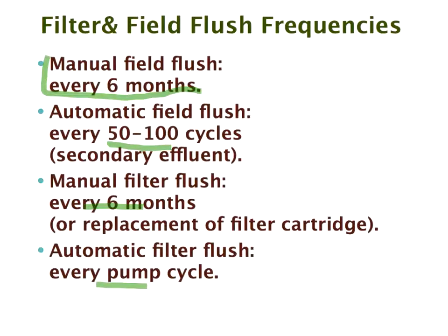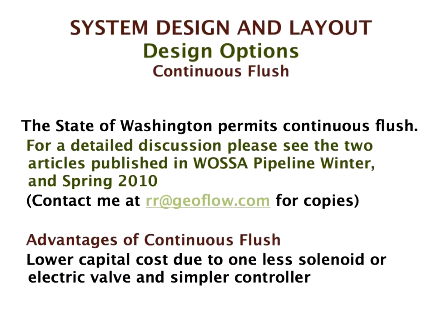And the filter flush is usually set up every pump cycle. Again, it doesn't cost anything. The cost is comparatively small. So if you have an upset and a pile of rubbish comes through accidentally, then just get rid of it straight away. There's no point in not doing it. As I say, the cost is virtually zero. If you want to argue that your solenoid valves are going to fail quicker, yes, they will. But instead of lasting 20 years, they'll last 10.